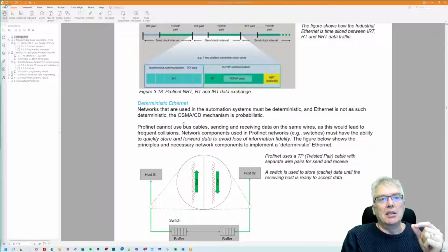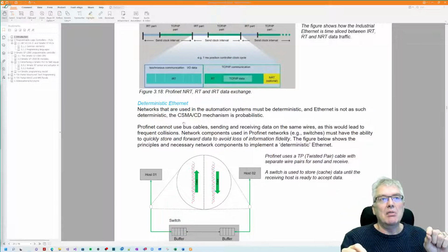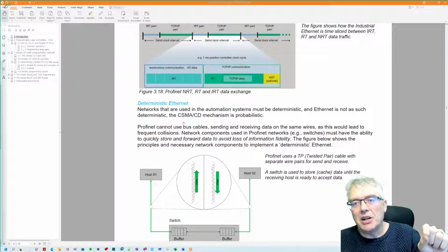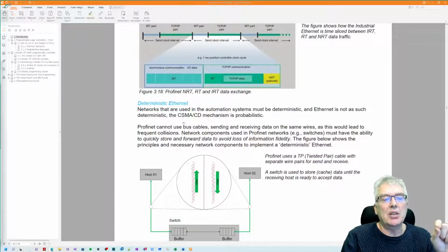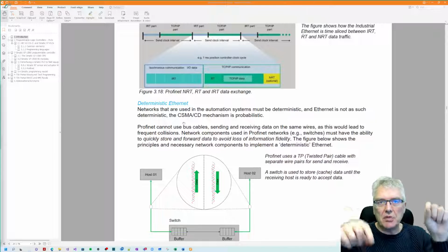Now, if you're not reading back what you are transmitting, someone else is destroying your communication here. And that's the collision detect. When they detect the collision, the device that detects the collision just jams the bus. Jam the bus means that they just garble the information on the bus. So those who are sending and listening on the bus read just nonsense.